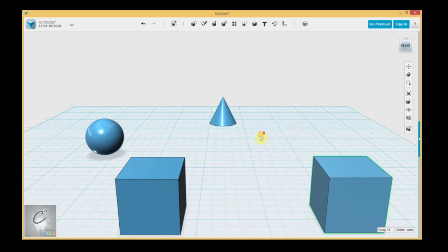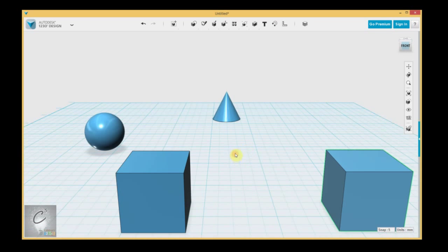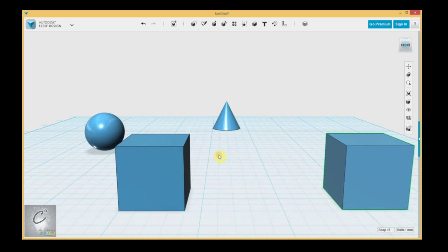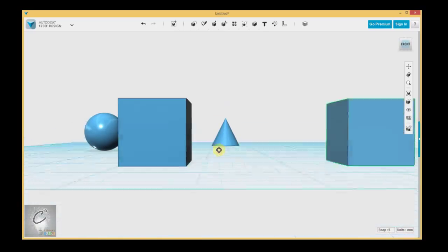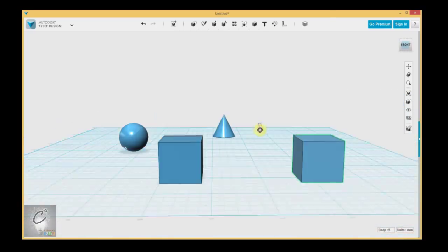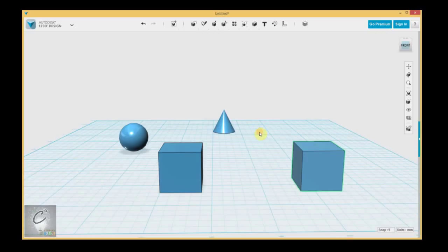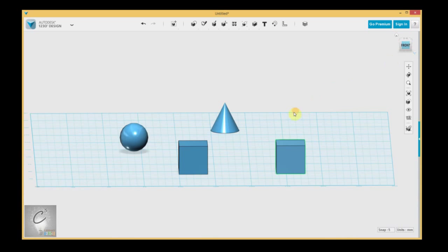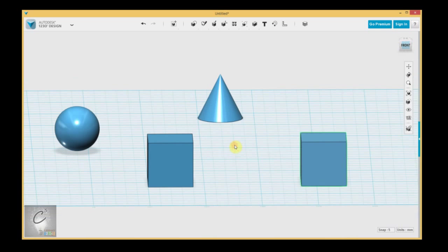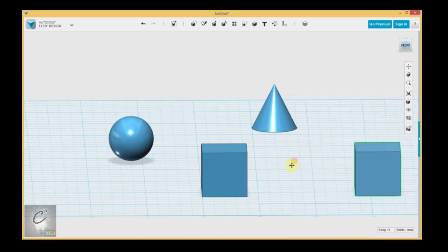But sometimes when you're designing, you want to get a real sense of what the actual measurements of these things are relative to each other without regard to how far away they are. So down here in the little drop-down menu under the view cube, you can set it to orthographic. Right now we're in perspective, and if I set it to orthographic, it's going to look a little bit less natural when we're just looking at it from an angle.